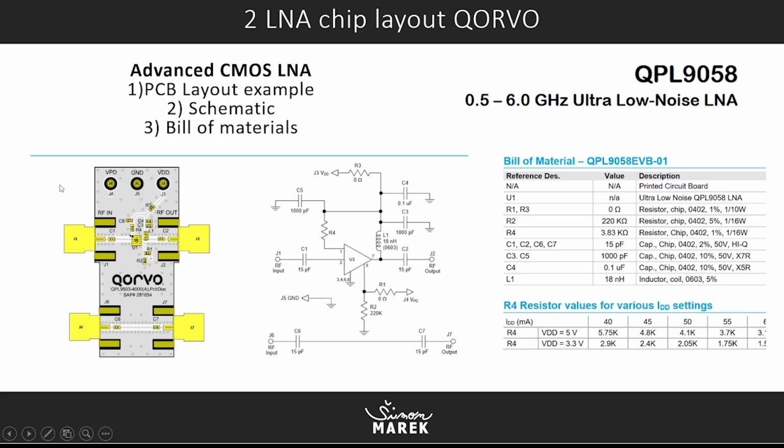Here in the top section there is our actual circuit, and below there is just a trace which connects two ports, though with some coupling capacitors. This is just for matching to 50 ohms and for easier setup of your instruments if you want to measure it. This way you can prepare your VNAs or your test instruments.